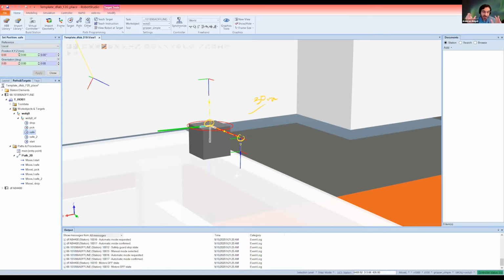At this moment, it doesn't make that much of a difference. The only problem is that when you're using the world coordinate system, Z is facing up. But when you're using the local coordinate system, as you can see, the blue is facing down. So you should be careful about the numbers that you're using. But just for the sake of having some sort of tradition, let's use local, because then in rotation, it's also really important. And you see that the positive Z is facing down.